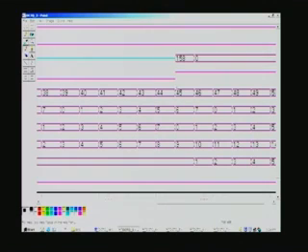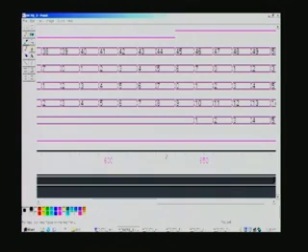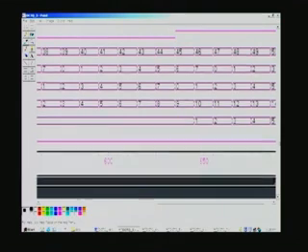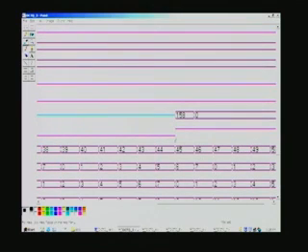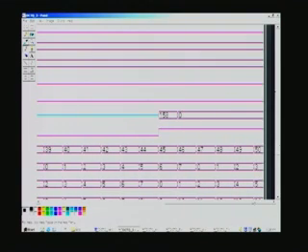At the start it was 185 nanosecond, now let us see how much time this is occupying here. This one is 635 nanosecond. So, if you take the difference, you get precisely 450 nanosecond, which means 45 clock cycles, because our time period of 100 megahertz is 10 nanosecond, and precisely after the latency of 45 clock cycles you have got the first output, and this is the DC coefficient, balance are all AC coefficients, and there will be totally 64 in number. If you go through that, we will go into the other waveforms.